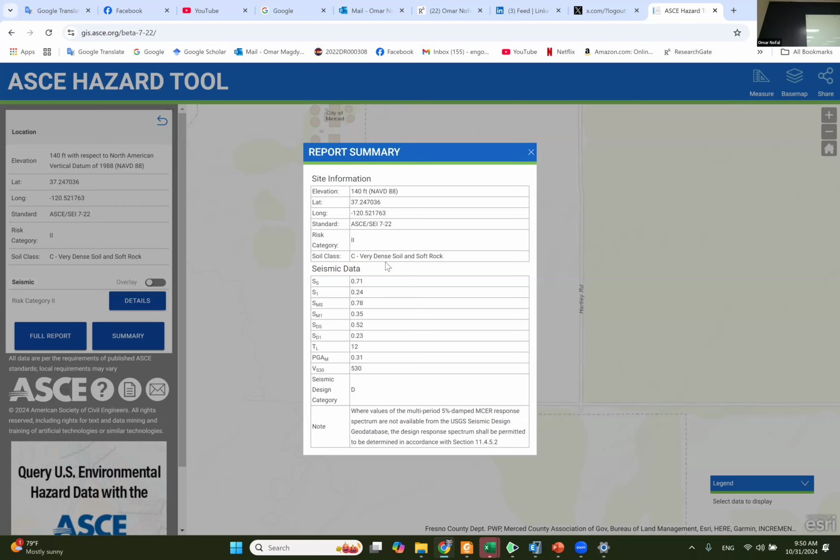And then it tells you what the long period is, like what is the maximum period. It's like 12 seconds in this zone. And I believe that's everything you need. Okay, so let's see. So that's the tool we're gonna use, and then we pick the parameters and go to ETABS and apply this load on the building. But we need to define this load first before applying it, okay? All right, so let's see how we do this, okay?